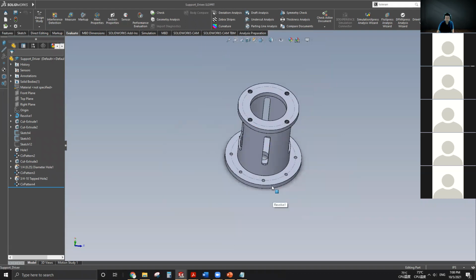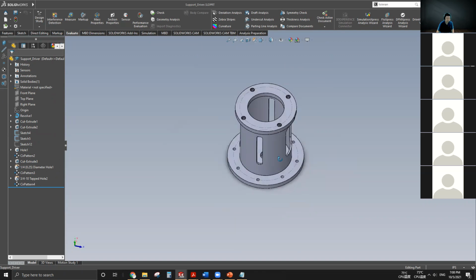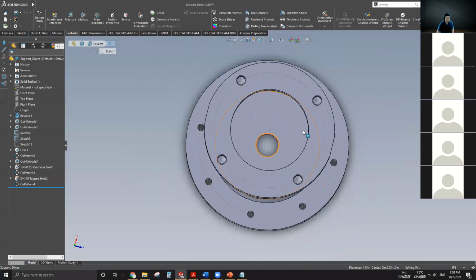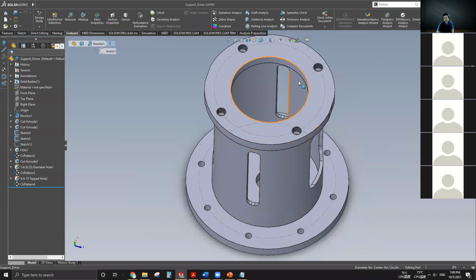We don't want whatever liquid from the bottom to come up. We call it a mechanical seal, but I'm not going to talk too much about that. That's why the bottom bore is well controlled, but the top opening is not, because we can open it even bigger, just leaving enough material for the flange connections, so that we can optimize it to have the least weight.